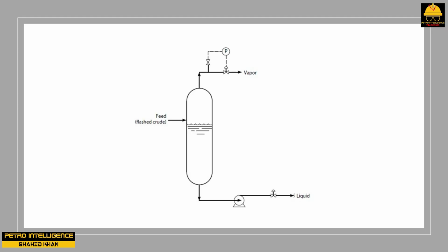Temporary solution. Increase in NPSH. This pump is presumed to run fine once it is running. The available NPSH is such that it exceeds the running NPSH. So how can he provide a temporary increase in the available NPSH to satisfy the temporary starting NPSH requirement? The answer is to suddenly increase the pressure in the drum by partly closing the back pressure control valve shown in the picture. This will instantly increase the pressure at the suction of the pump.